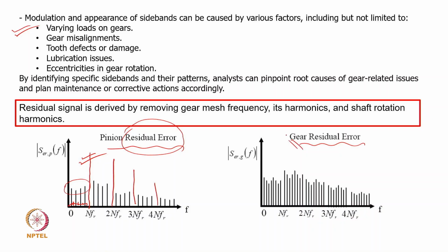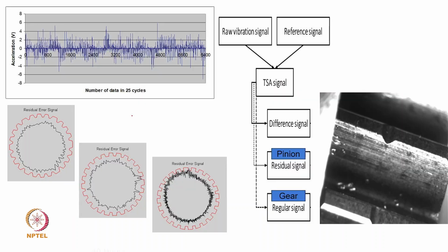So there are methodologies and algorithms in which the residual errors are analyzed, and that will also be useful. We also showed the residual signal in a similar lecture, when we were getting the vibration data for the gear pair. Maybe at 0 hours we get some signal, at 40 hours we get some sort of signals, and at 100 hours we are getting a shift in the signals.